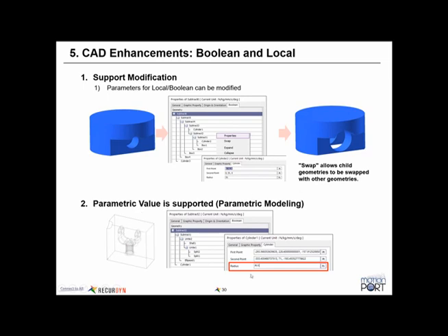And then in conjunction with all that, you can have parametric values as part of the basic pieces of geometry, which means you can have a parametric value actually morphing the geometry. We didn't have this capability to do it this way before. So this can be, I think, very powerful. Thinking back to the DOE, you can set up a range of runs where you're actually morphing the geometry as well as other characteristics of the model, like spring stiffnesses or whatnot.